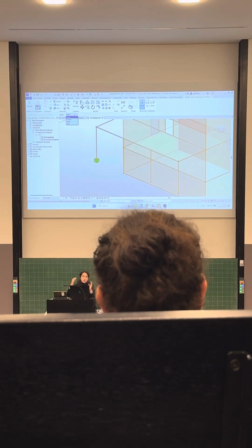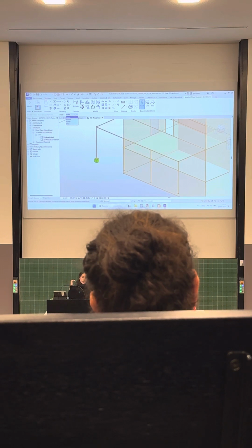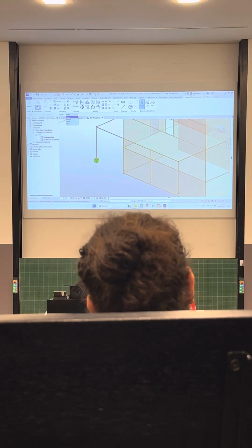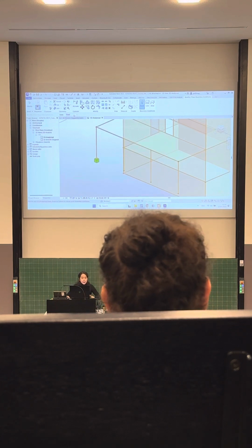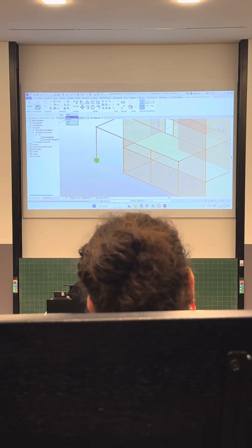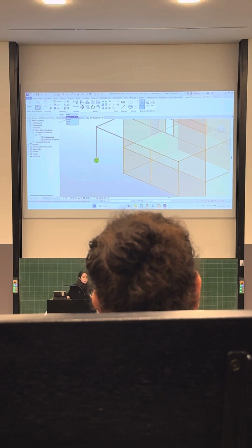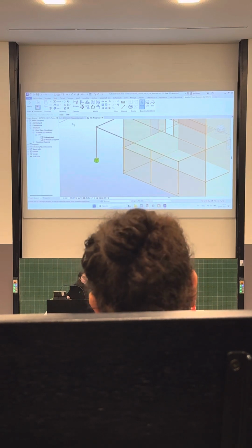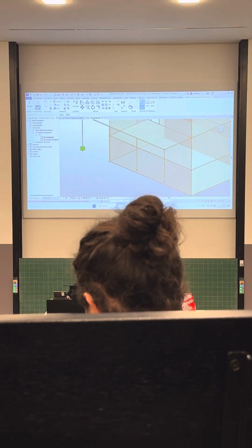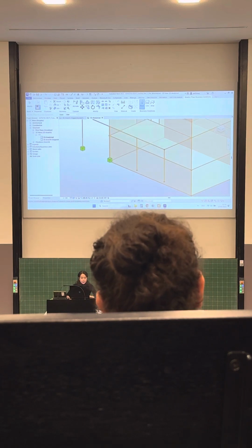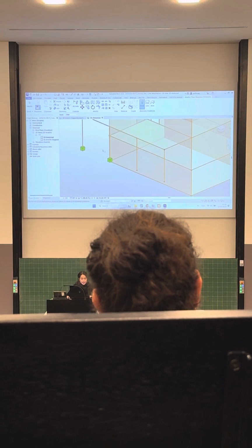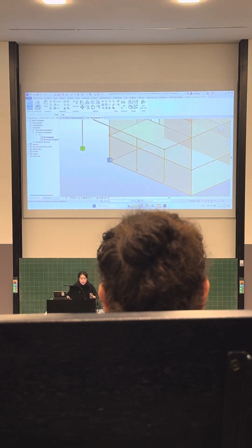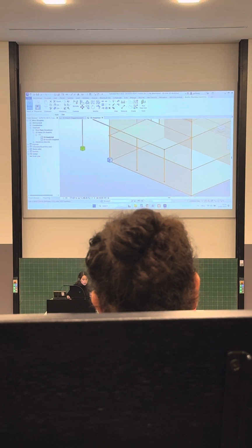But in case you have beams on the roof, it can be pinned, or you have a different type of foundation, you can choose here whatever you want. If you have specific stiffness for your foundation, you can choose user and put it. And now I press escape and click on it.